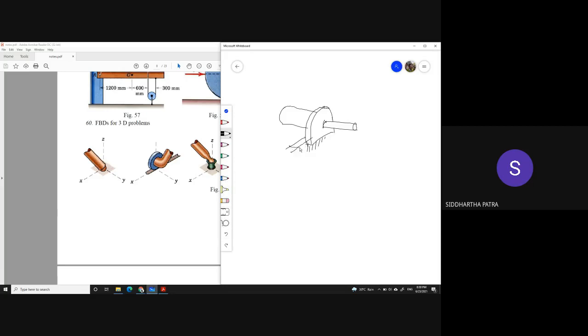of the support is substantial, okay, then you are correct in thinking that there would be no rotation about the x-axis or z-axis, because again the cylinder has line contact with its support, or itself has this cylindrical surface contact with its support. Okay, this is the contact area, and you are correct in thinking that the rotation about x or z would be impossible.